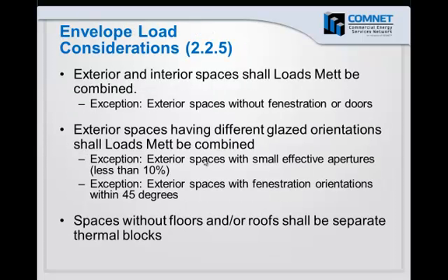Some considerations for thermal blocks and envelope loads. In general, exterior spaces and interior spaces should be separated into different thermal blocks. But there's an exception for cases when the exterior space does not have any fenestration or very little fenestration.